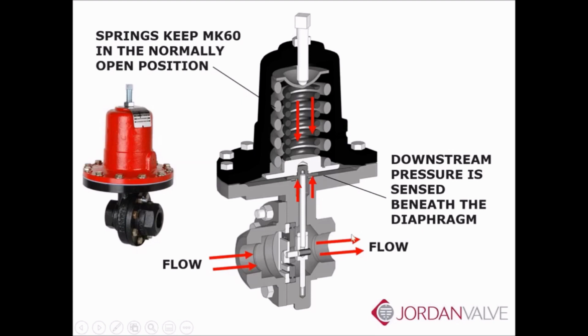So the sizing program we just did sizes control valves, sizes regulators. It doesn't discriminate between the two. It's more of what is your percent travel, what is the accuracy needed for the application, is feedback needed for the application, that kind of dictates control valves versus regulators, but the sizing program calculates Cv for both.